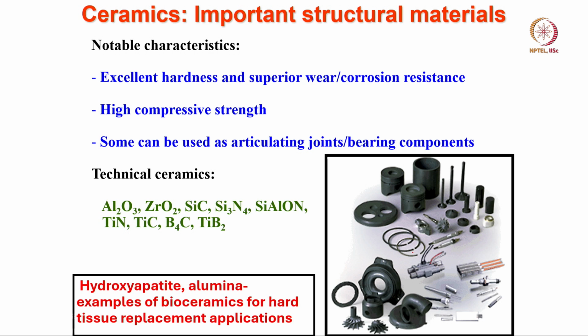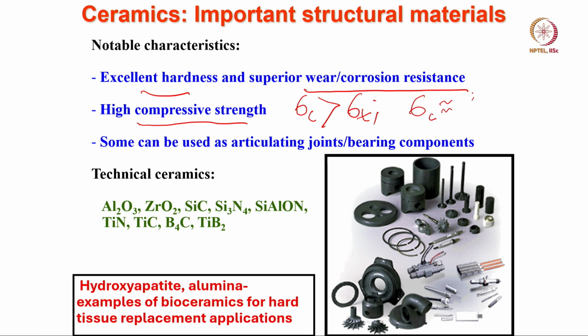It has excellent hardness, wear resistance, and corrosion resistance. It has a good compressive strength. One of the things that I must mention is that, compressive strength wise, ceramics under compression is much higher than in tension. In fact, one can derive and show you that the compression strength of ceramics is at least 8 times that of the tensile strength.